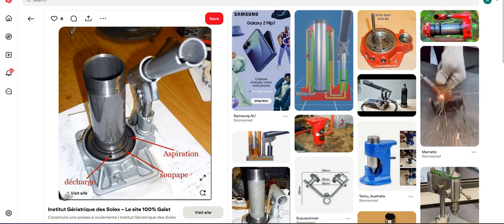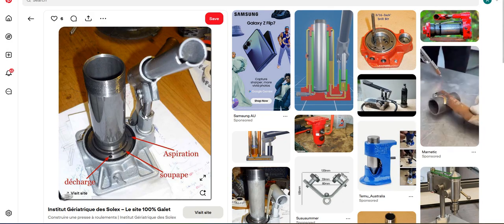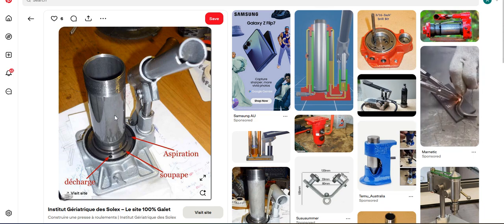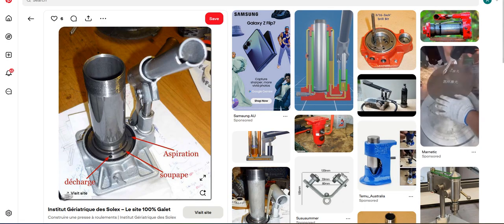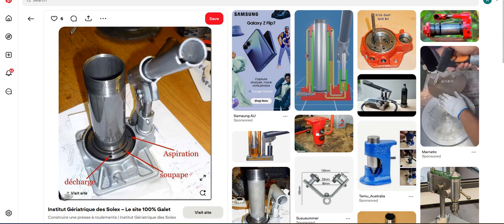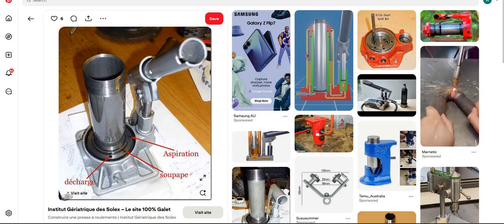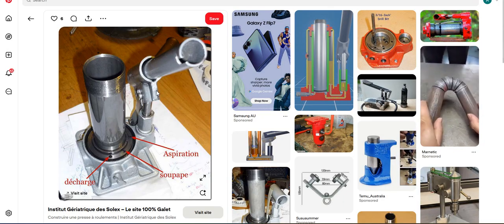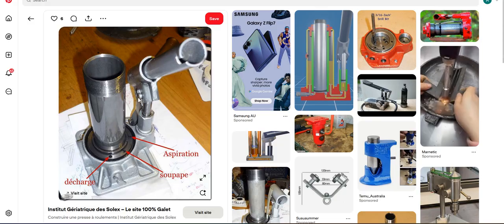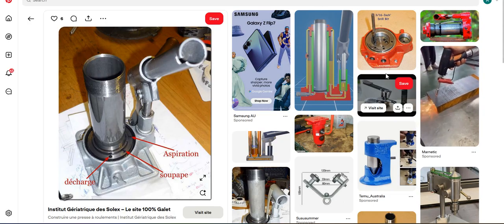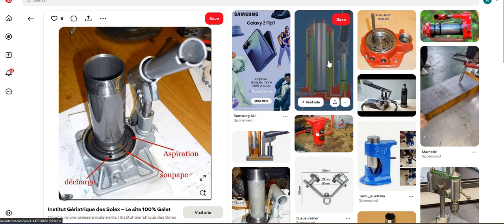This cylinder is going to be a hardened bar, which is going to be machined to the dimension. Of course, all these dimensions are going to be critical because we have moving parts, so they should have very high tolerances in their manufacturing process. We have a thread here. This pipe is going to be done mainly by the rolling process. This part is going to be a plate forming process and welding from one side, and then we're going to have some punching to fit this pin with the side cylinder here to keep the bumping effect like what we see on this side.